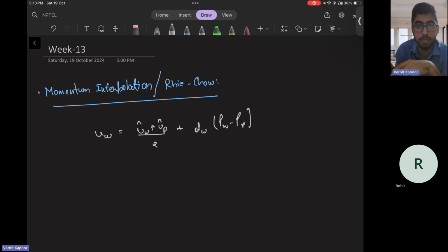So momentum equations still support checkerboarding, but momentum interpolation results in artificial terms, which help us in solving the problem. The staggered grid approach can also be shown to have this diffusion-like term, avoiding the oscillation from checkerboarding by modifying the continuity equation with an extra term, the fourth derivative of velocity, a diffusion term.